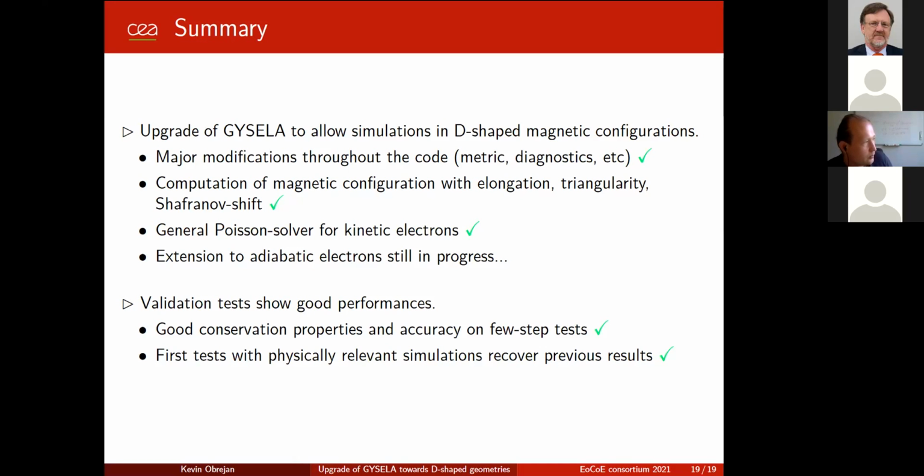So the solver that you're using is then CG based, right? As we've discussed with Eric. Yes. Okay, so this will not be scalable. You're aware of that. CG cannot be scalable on the Poisson equation. Yes, that's actually one of the main issues. I already had a slide for you, but I didn't mention in this presentation the fact that computation time is one of the issues we have. But going for a Poisson solver, there is all the knowledge about multigrid that you cannot beat multigrid with a CG solver.